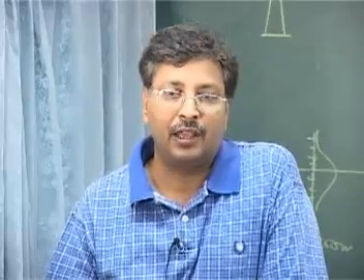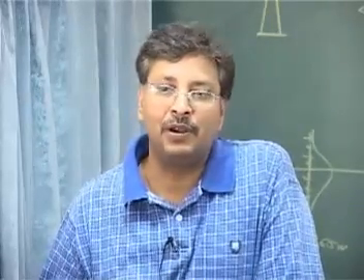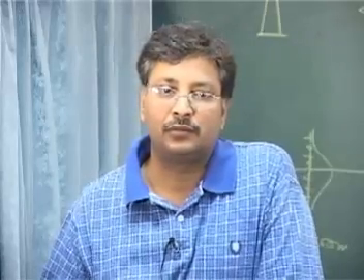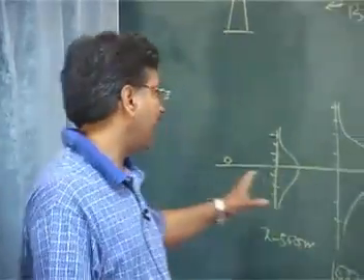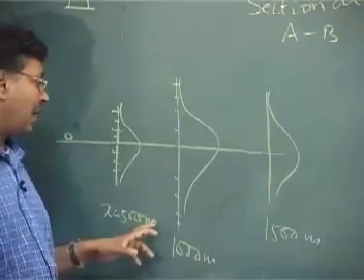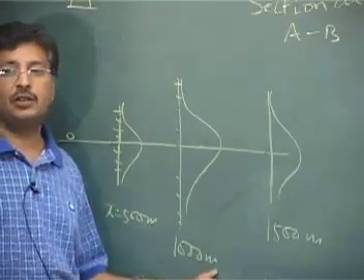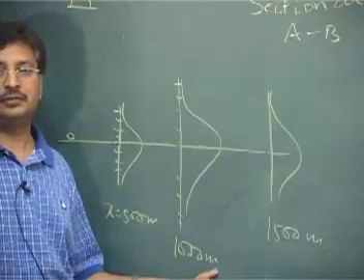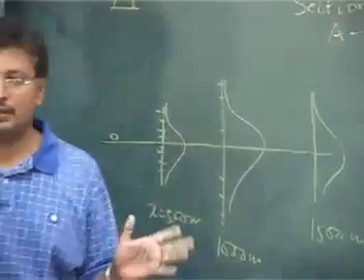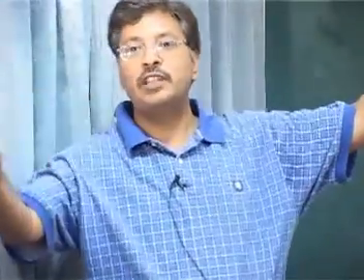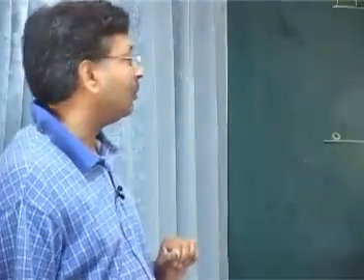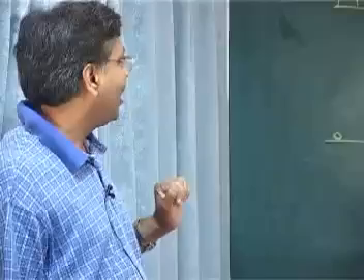And what else will sigma y and sigma z depend on, other than the x that we are seeing? Tell me, with x, will sigma y increase or decrease? Increase. So that is one thing that is clear: because the plume is expanding, sigma y is increasing. What else will sigma y depend on? Turbulence, and turbulence is indicated by the atmospheric stability.